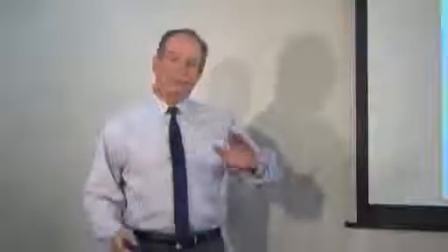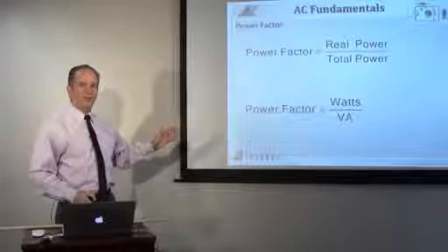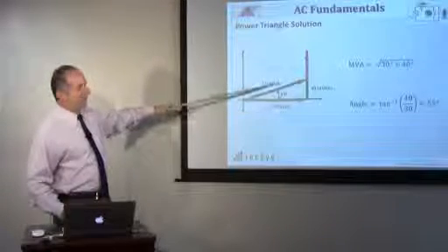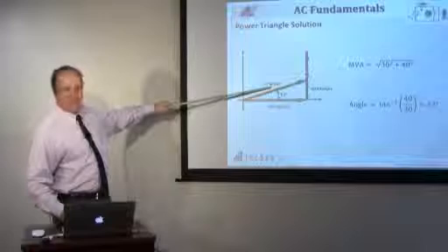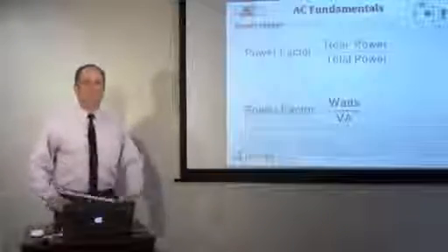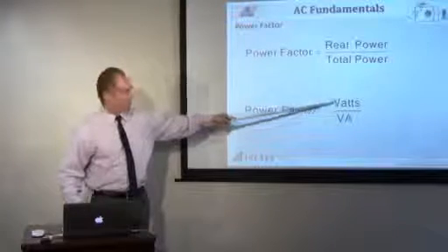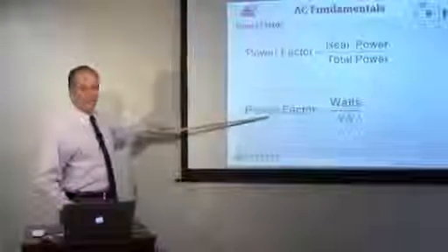Okay, and one of the last terms to know in AC fundamentals is this term called power factor. Power factor is the real power divided by total power, or the watts divided by VA. Now I'm going to switch back to the previous slide for a second to show you something here. The small number divided by the big number. The watts divided by the MVA, or the watts divided by VA, is power factor.